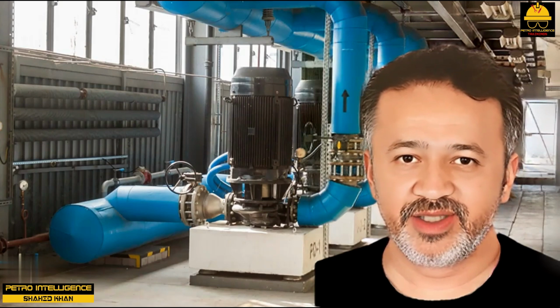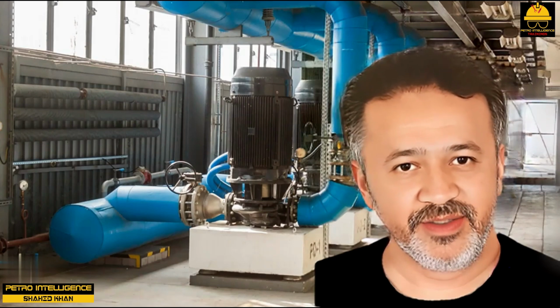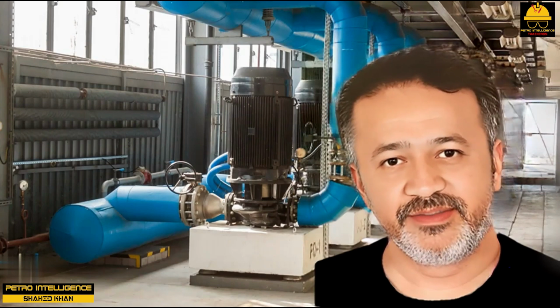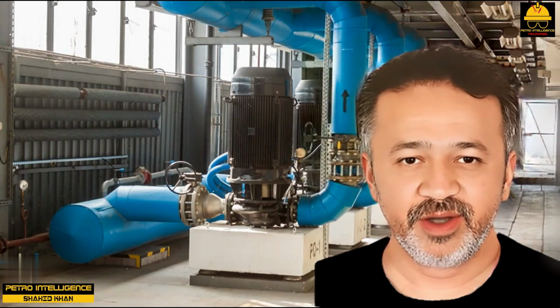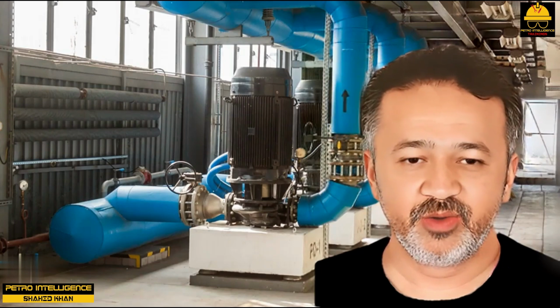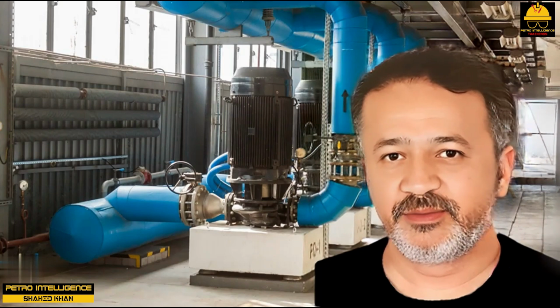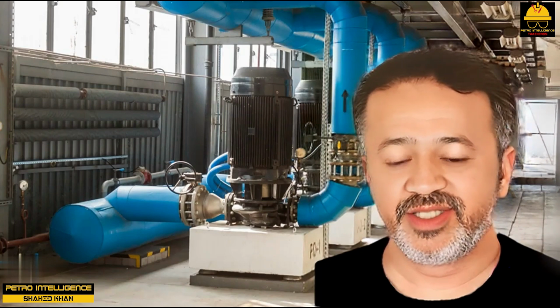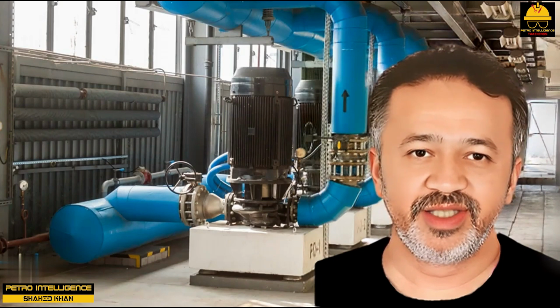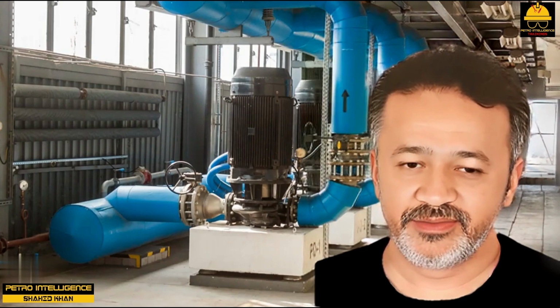The feet of head developed by the pump is not affected by the specific gravity of the liquid, but the weight of liquid pumped is proportional to the specific gravity. If the specific gravity drops by 40% and the liquid volume, GPM, stays constant, then the pounds lifted by the pump drops by 40%, and so does the electrical work.